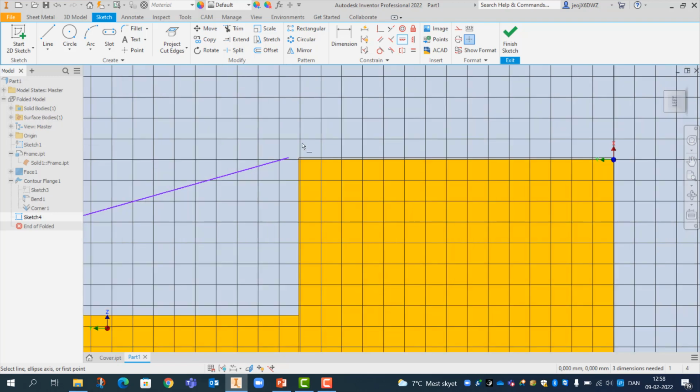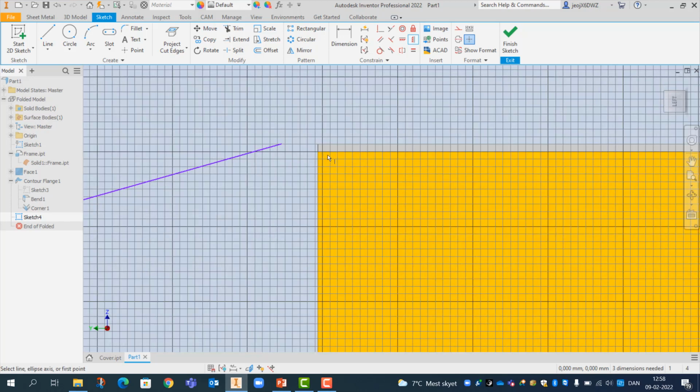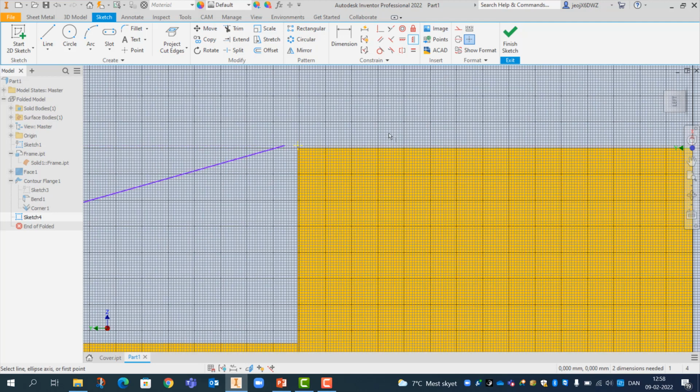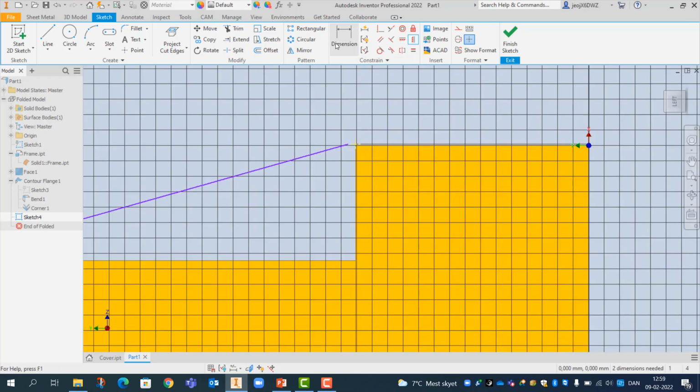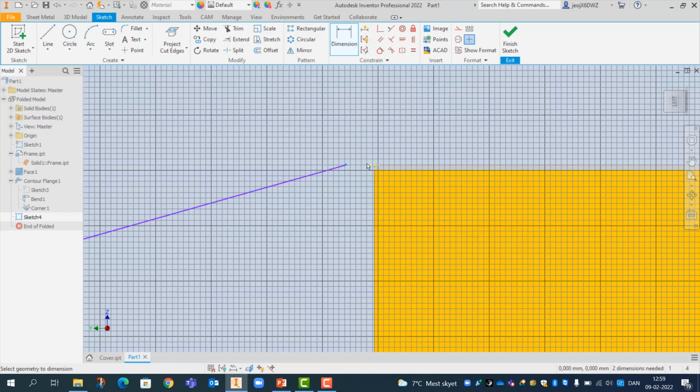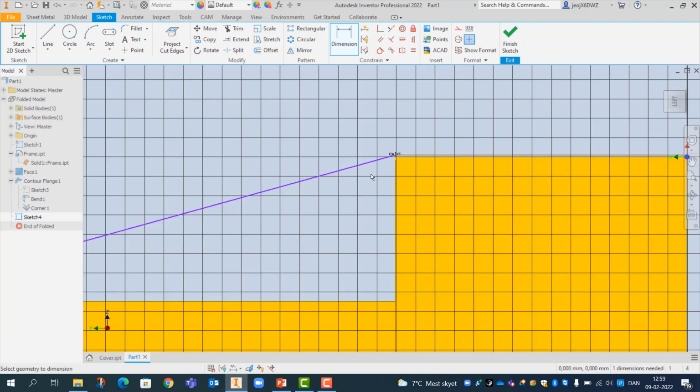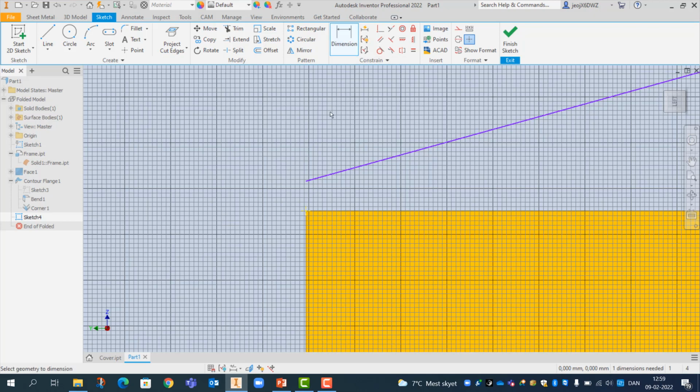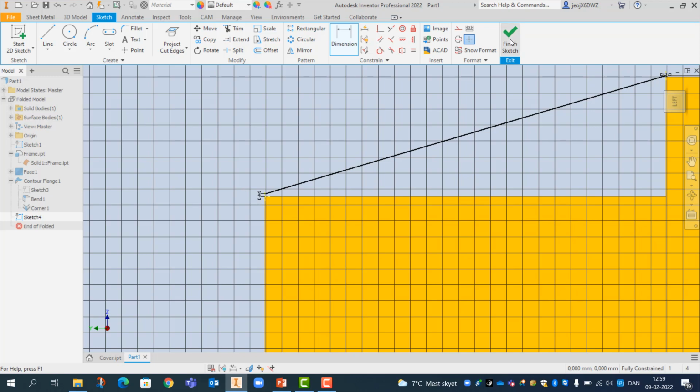We got the same situation, and then it should be vertical, because of this, you can see it from the cube, and I actually turned it, that's why vertical is horizontal. So vertical is of course still vertical, if you look at the cube here. Dimensions needed, use exactly the same ones. I think this was the 1 millimeters, and down here we had the 4 millimeters, like that, fully constrained, perfectly fine.